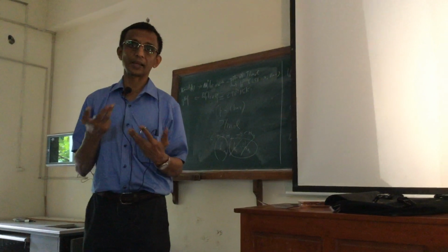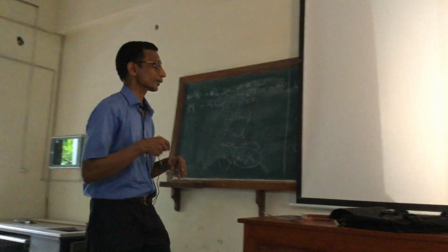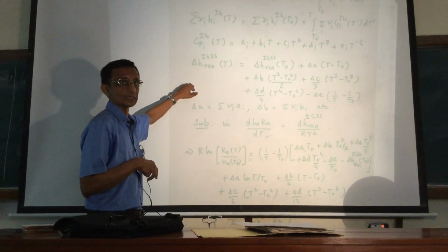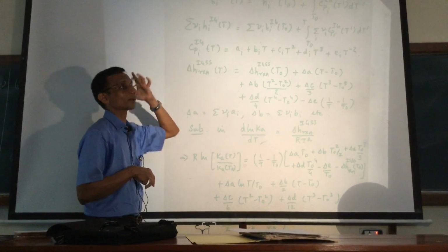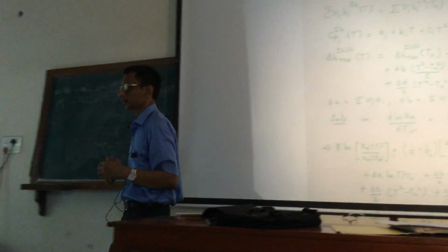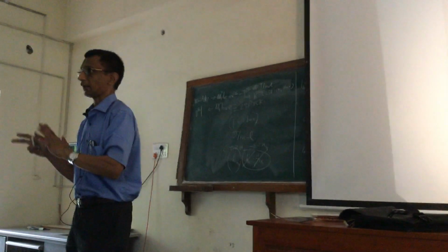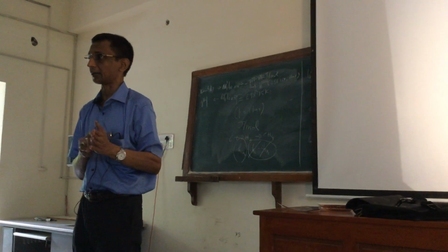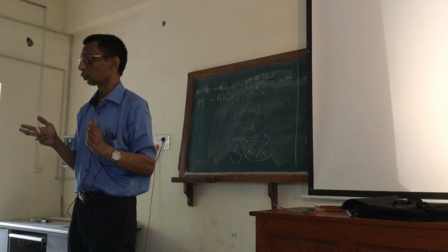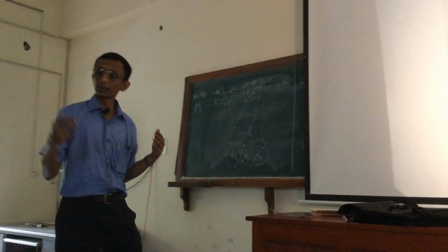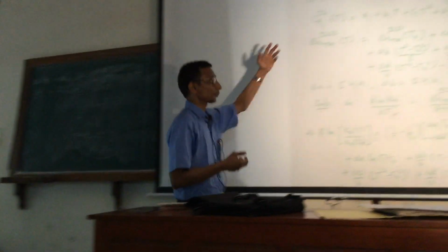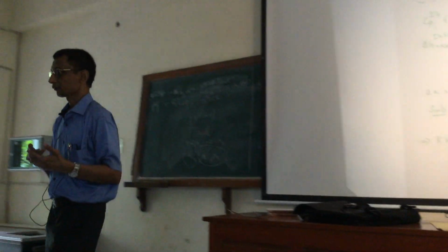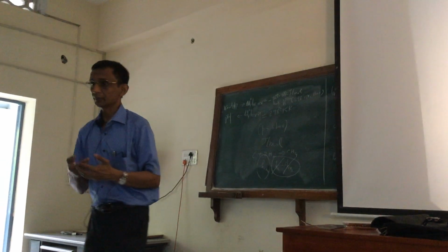But it is there in the standard textbooks, so you can easily get it. So it's a fairly tedious but straightforward procedure. All I have to do is get the specific heat data, because all it requires is calculation of enthalpies at one temperature given at another temperature for the ideal gas, which we know very easily how to do. Once you have it, it's a question of multiplying by the stoichiometric coefficient, summing it, and then integrating again. Right?